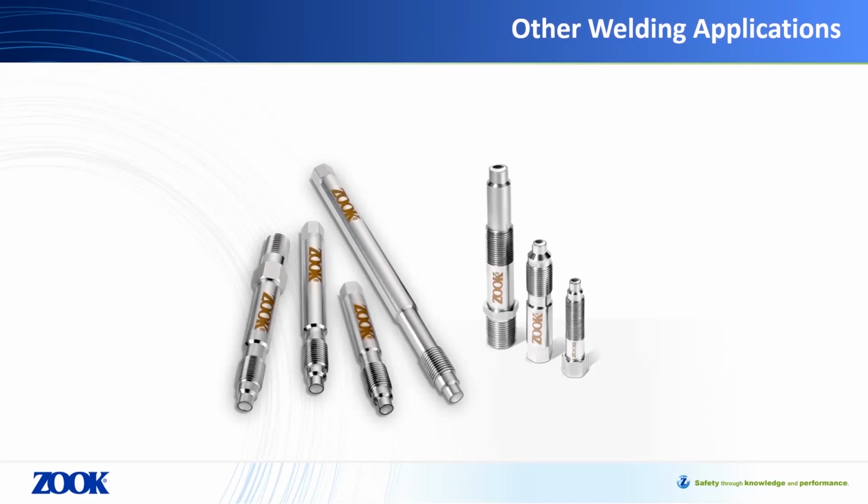The reason that this is particularly noteworthy is due to the ability of a welded product to allow the rupture disc to be positioned immediately at the process media. This ensures that the rupture disc is in intimate contact with the process. This is important as it eliminates the risk of process media buildup, which may impede the performance of a rupture disc or cause it not to burst at all. The ability to do this is something that is only possible in a welded product.